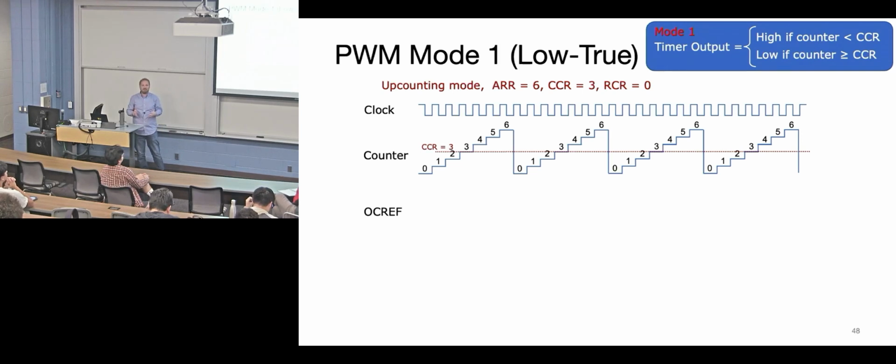What would be a reason why you'd want to reduce the clock speed coming into a timer? Maybe the thing you're trying to compare the timer to is going slow, or going too fast. If you have a 16-bit timer and maybe 100 megahertz is coming in, your timer may expire or wrap around before your event has occurred, right?